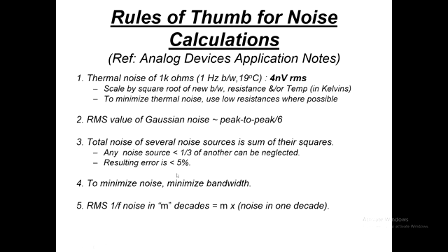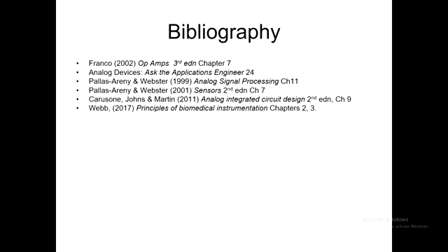And the major takeaway point is to minimise the noise, minimise the bandwidth, because that's one thing that we have some control over. We can't usually change the temperature too much. Anyway, okay, enough of that.